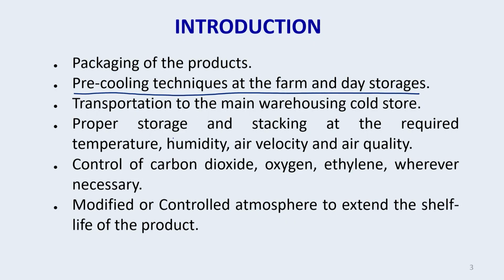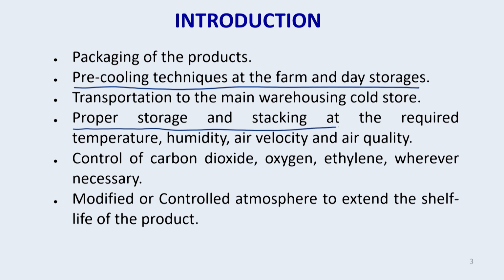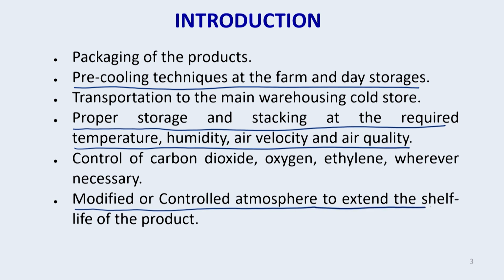Proper storage and stacking in the cold room, at the required temperature, humidity, air velocity and air quality. This is very important. The storage conditions vary from one product to another. The temperature requirement will be different, the humidity requirement will be different, and it varies from one commodity to another. Control of carbon dioxide, oxygen, ethylene, wherever necessary. Modified or controlled atmosphere to extend the shelf life of the product.